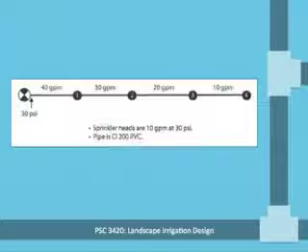In this example, notice that each sprinkler has a flow of 10 GPM, that's given to you here, and that they're all on one lateral line. So let's consider what the flow would be in the sections of pipe between the sprinklers. First, between sprinkler 3 and 4 right here, the flow required to operate sprinkler number 4 is 10 GPM. Again, that's given here. So that's the amount of flow in this section of pipe.